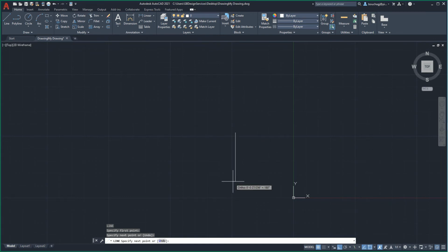This tool is extremely helpful in ensuring that all linear geometry drawn horizontally and vertically are always truly horizontal and vertical. Unless there is a specific reason to be drawing an element in a direction other than the 0, 90, 180, 270 degree directions, keeping this tool always active is recommended. The F8 key will toggle this tool on and off.